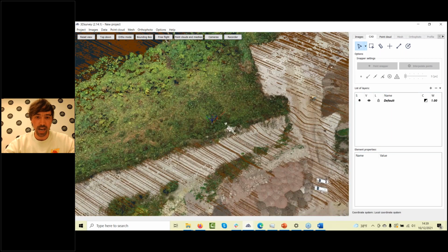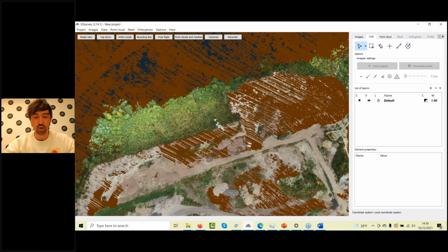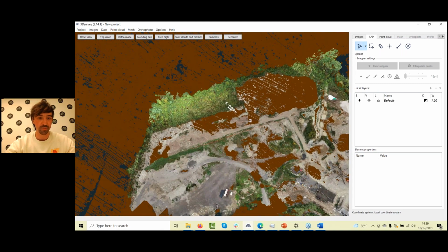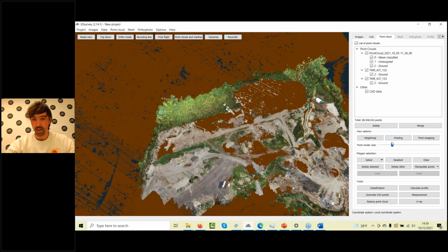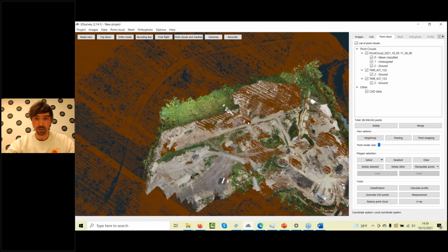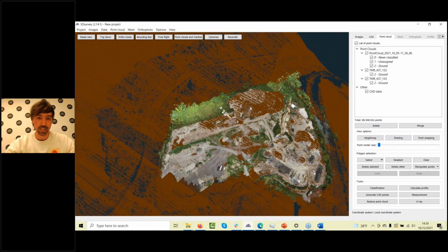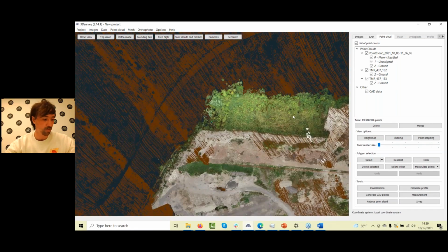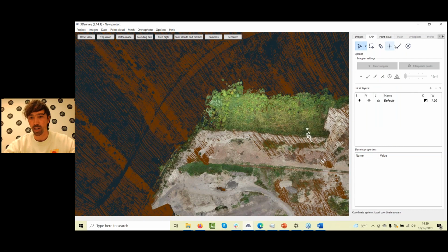What was my idea here is to show you how to combine those 2 data types and generate the best possible surface. If I go back to the point cloud tab and first just create my areas where I would like to combine the data, I will go to CAD, create a new layer, let's say LIDAR area, and make the layer active.